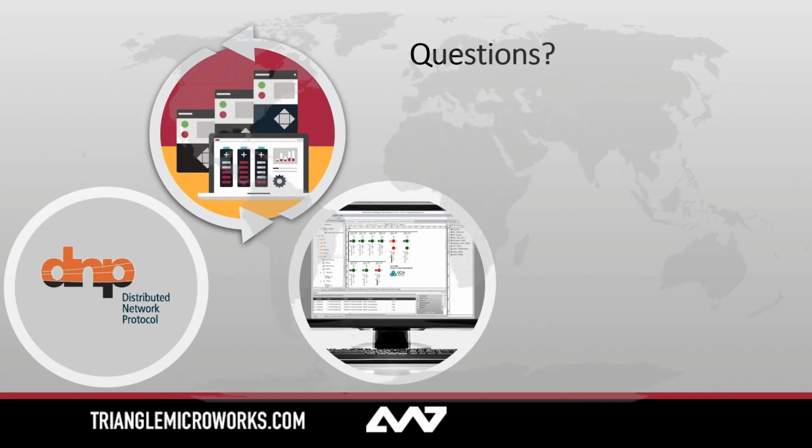If values change, it's automatically going to push out the reports. So it's going to behave just like a 61850 server should. And as for cleansing your files, we try our best to pull in any sort of SCD file or SEL file that we can. If it is incomplete and has some missing fields, or it's not up to a certain standard, we may not be able to pull it in. That's when you would use something like Navigator, another tool we have.